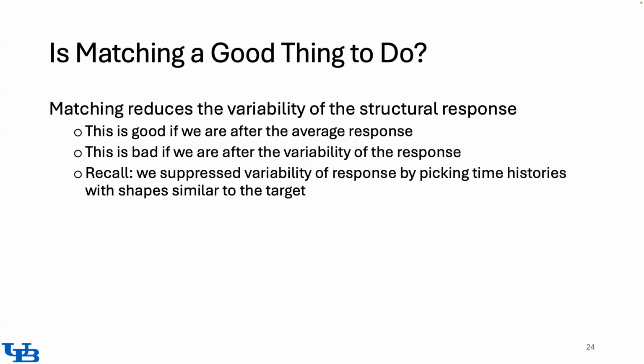But if you want to use some types of time series to do a fragility calculation and develop a fragility curve, then the shape of your fragility curve that you get, where you have, let's say, PGA and then the probability of collapse, to get the actual shape, which also involves the probability, not whether it's one or the other, then maintaining the variability is actually important.